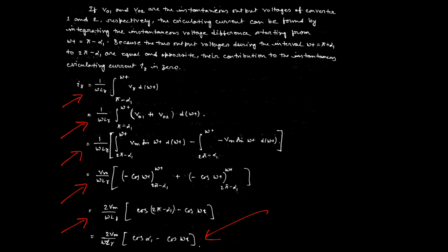So the circulating mode operation, inverting mode operation or rectifier mode operation depends on this particular value alpha 1. Now consider alpha 1 equal to 180 degrees. Then the first converter starts working. If alpha 1 equals, suppose, 0 degrees, then the second converter starts working. If alpha 1 varies from 0 to pi by 2, then the first converter can provide the positive current.